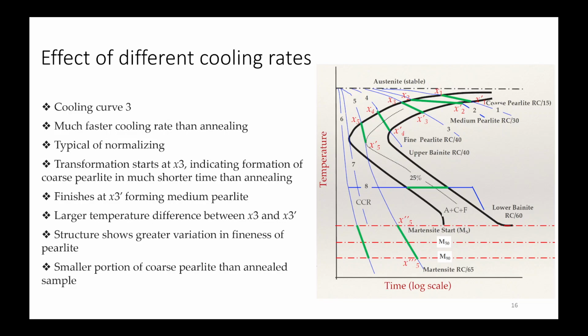No, similarly, as I told earlier, right? As you were saying, there's formation of void or something. As soon as you start talking about voids, another interstitial can come. But we are not talking about interstitial here. We are talking about substitutional type of structure. Substitutional means another element's atom will come and sit at another's place. That will be easier if, for example, copper is FCC and nickel is also FCC. So nickel will sit at copper's place and both have FCC, then it will be easier even if there is 50-50% of both of them present.